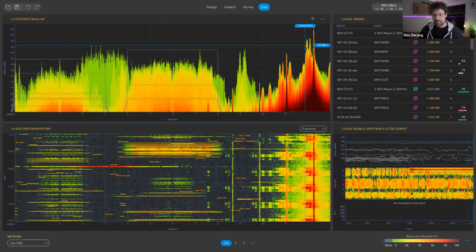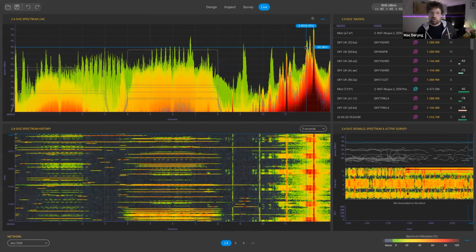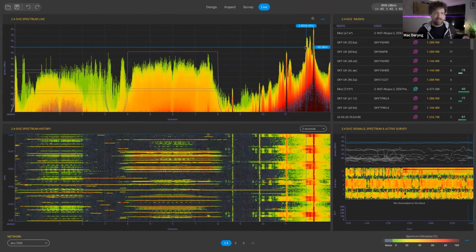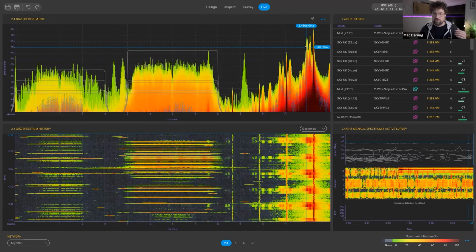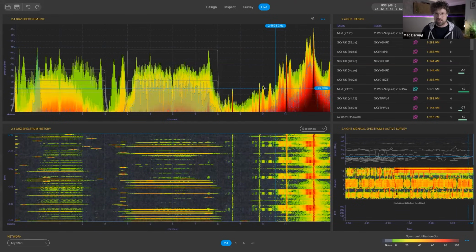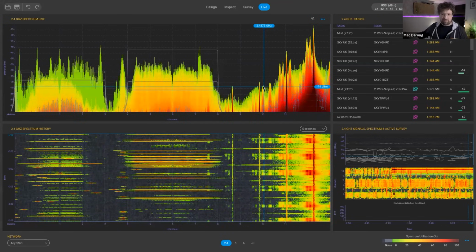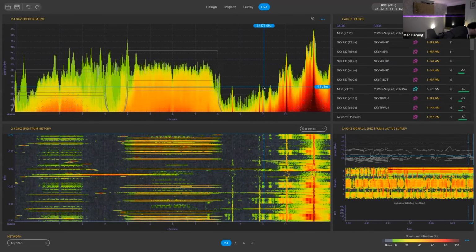I don't know. Now, guys, my camera is close to my Sidekick. So my Sidekick doesn't have enough SNR from beacons, from the access points, to be able to demodulate that stuff on channel 11, because I'm killing it on channel 11. Now, I will move my camera farther away from the Sidekick. I will move my Sidekick farther away from my camera.